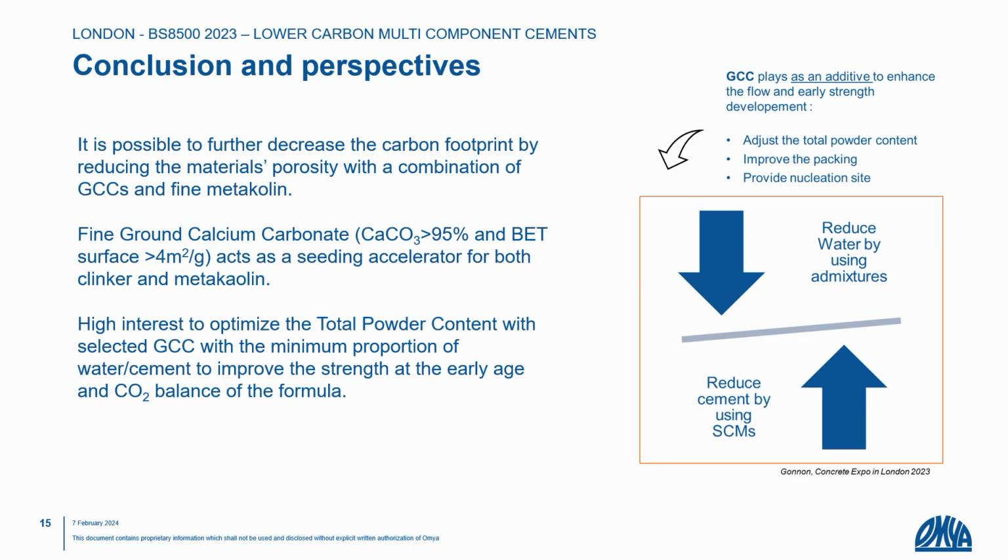But definitely keep in mind that in some parts of this world, we use ultra-fine calcium carbonate to solve some winter strength development issues. And I saw when we gave a presentation, Bill, in London 2024, that when I see the list of what I can do to wake up my system, ultra-fine calcium carbonate is not described, is not proposed. And we can do that.